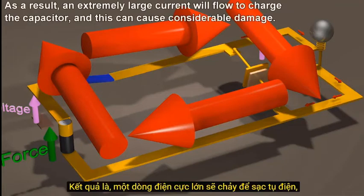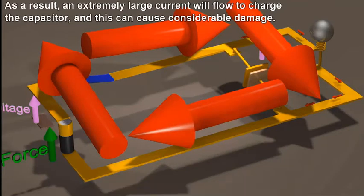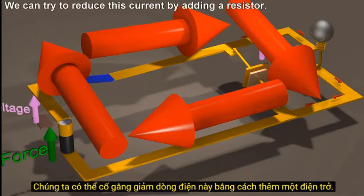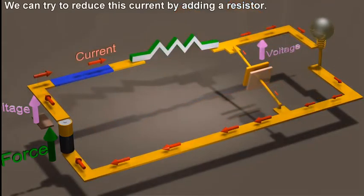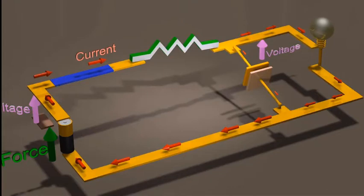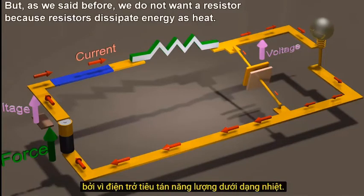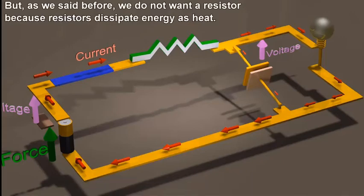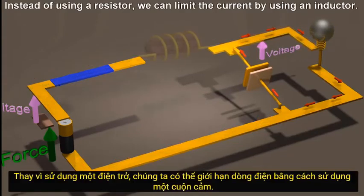As a result, an extremely large current will flow to charge the capacitor, and this can cause considerable damage. We can try to reduce this current by adding a resistor. But, as we said before, we do not want a resistor because resistors dissipate energy as heat. Instead of using a resistor, we can limit the current by using an inductor.